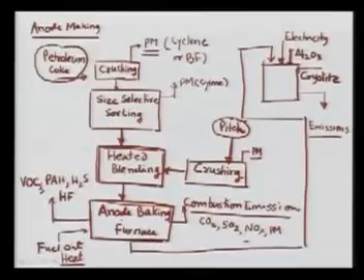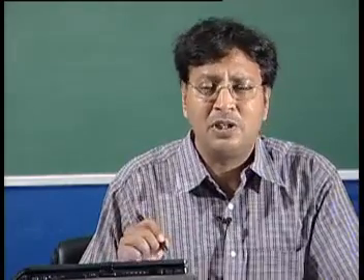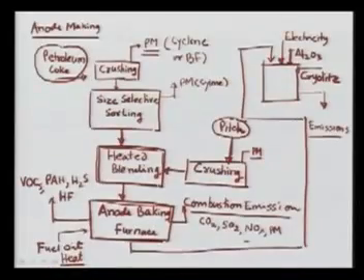So once you are heating it up, I am not calling it firing, it's the anode paste form being heated up, whatever volatile organic compounds you see here, the VOCs, will be emitted. VOCs can be benzene, toluene, or other organic compounds in the volatile phase, which are very, very harmful. You can also emit some PAHs, polycyclic aromatic hydrocarbons, and some hydrogen sulfide, because the coke will have a high amount of sulfur, and the pitch can also have sulfur, as you can see.